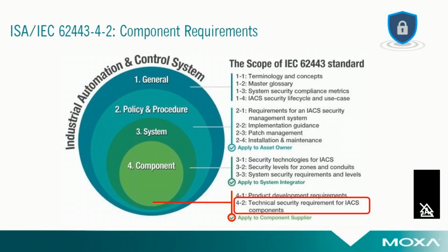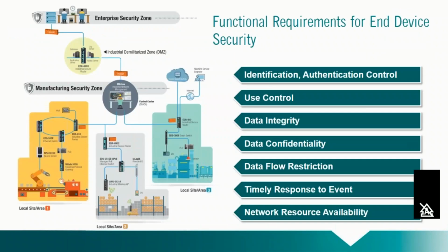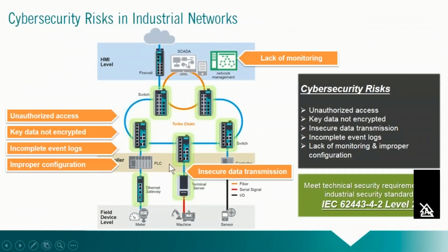So let's dive a little deeper, starting at the bottom, with 62443-4-2. We're talking about if you're buying new industrial control communications equipment, what types of security elements should you be looking for and implementing in your systems? These are 7 different functional requirement areas, and the system requirements of the 3.3 document. The 4.2 document specifies how these specific requirement enhancements are called out in each of these areas based on the security level compliance selected, SL1 through SL4.